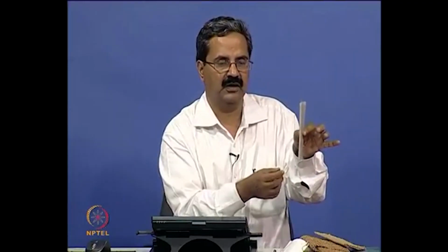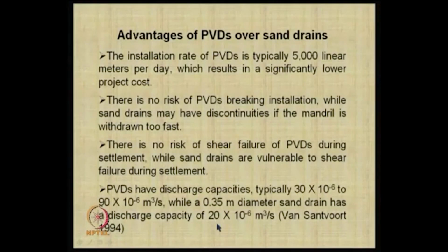Actually, the beauty here is that, as I just mentioned, this filter allows only water, all the clay is outside. So, only water goes inside. It is an excellent filter cloth, and the inside is an excellent drainage cloth, and all the water will come up, it gets pumped up. Either it goes down or it is all by gravity, anyhow water is released because it is open to atmosphere and then water comes out. So, you can see that the drainage capacities are quite